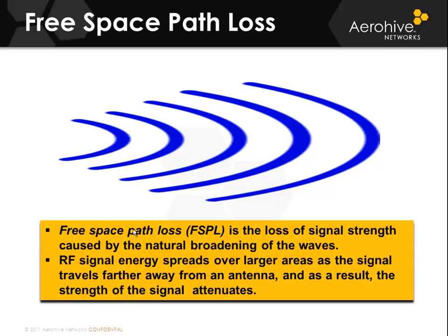Once the signal leaves the system, it's going to lose the bulk of its energy, much like a projectile leaving a barrel, where it loses most of its energy. The signal will lose most of its energy as it leaves the antenna. A signal will continue to travel, but with less strength, and at some point you might be able to pick up some RF energy, but you're probably not going to be able to use a reliable 802.11 signal due to distance from the transmitter and free space path loss.